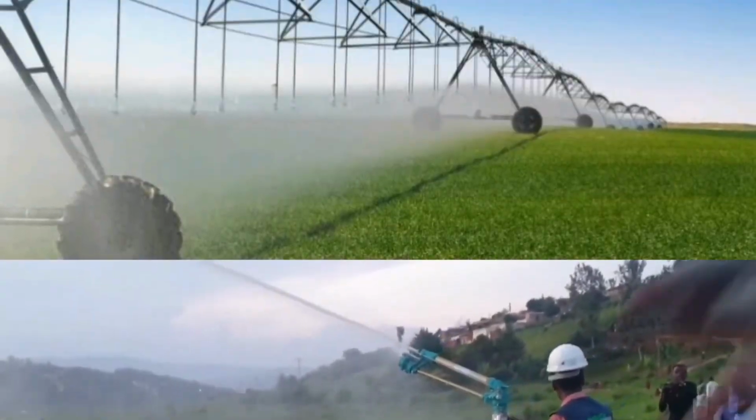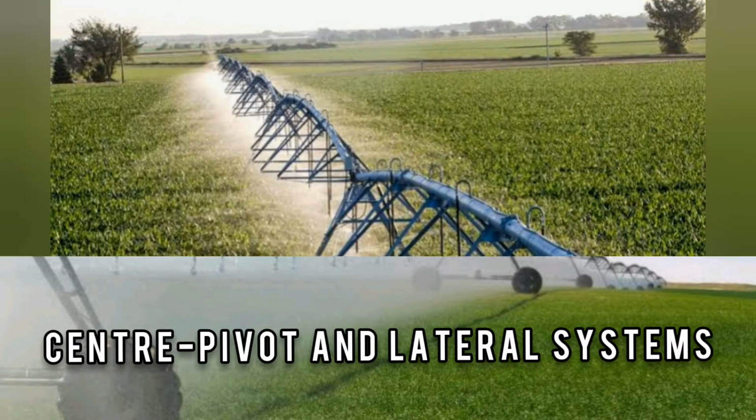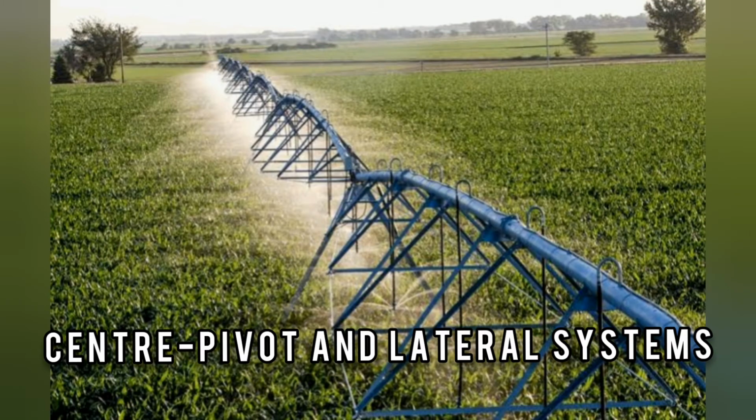The third method is center pivot and lateral irrigation. It is a form of sprinkler irrigation utilizing several segments of pipe joined together and supported by trusses, mounted on wheel towers with sprinklers positioned along its length. As of 2017, most center pivot systems have ropes hanging from a U-shaped pipe attached at the top of the pipe with sprinkler heads that are positioned a few feet above the crop, thus limiting evaporation losses.